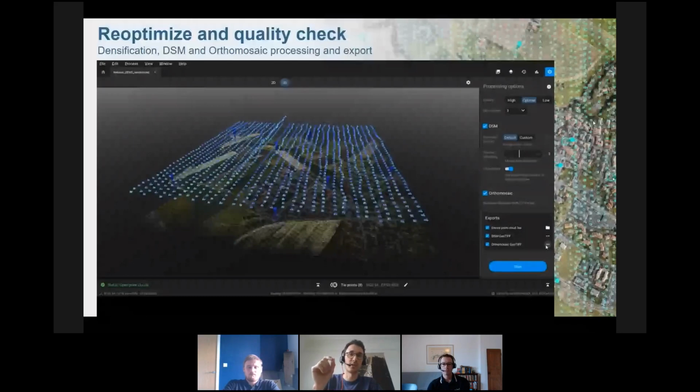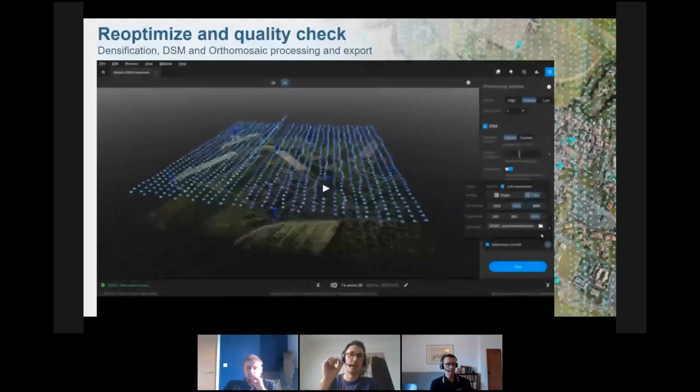And that's where it's really key here. Here it's important to pay attention because it's a good trick for those of you who want to use the automosaic as a background map. Maybe you need a more lightweight result and something that is more easily importable into third-party software. That's where you can have this image scale option in this export tab there. So you can compress it, and if you want to use it as a basis for vectorization, you can also export the full resolution, and you can also select the tiles, the tile size, and so on.